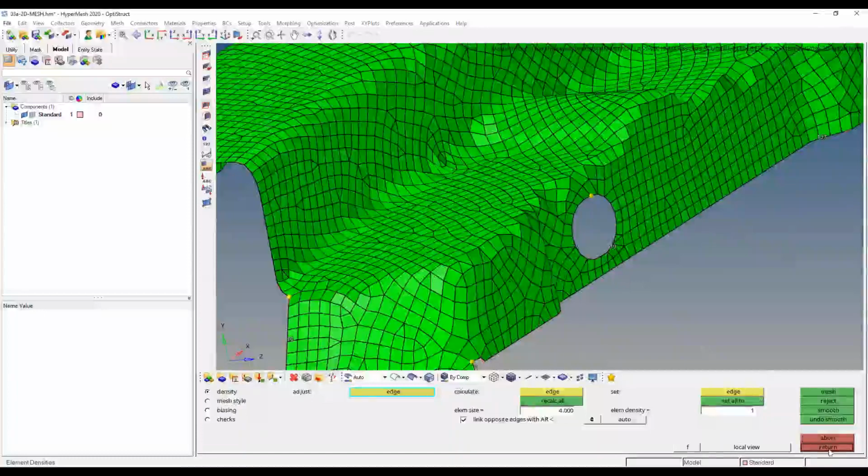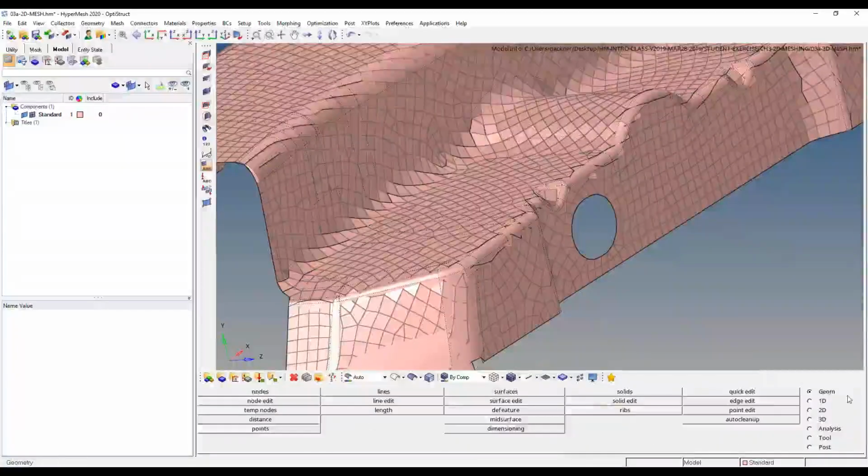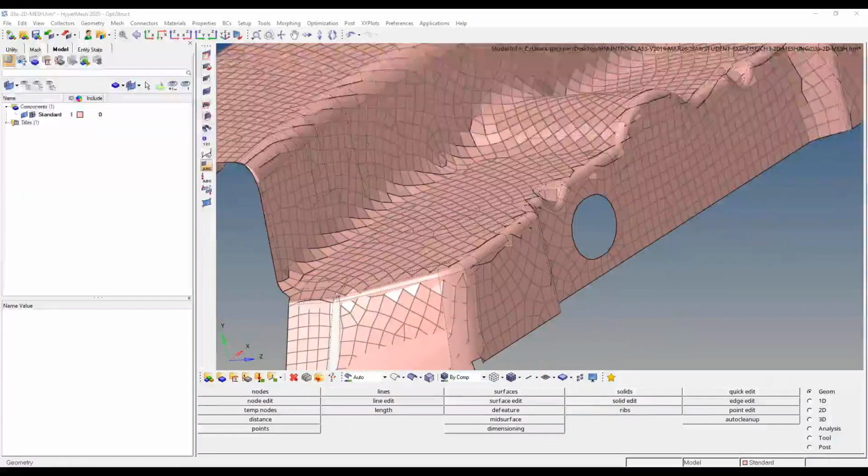Yeah, and then before we take a quick break here, there's that second question from Rahul about the ratio. I don't know if it's in their documentation, but I know it's in our FEA practical aspects guide. Yeah, 10% is the rule of thumb that I've been taught. That's a good one for a ratio of trias to quads, and if it's even 15 or 20, Rahul, I don't want you to think, oh no, I have 20% instead of 10%. It's not as obvious to just have a number listed there.